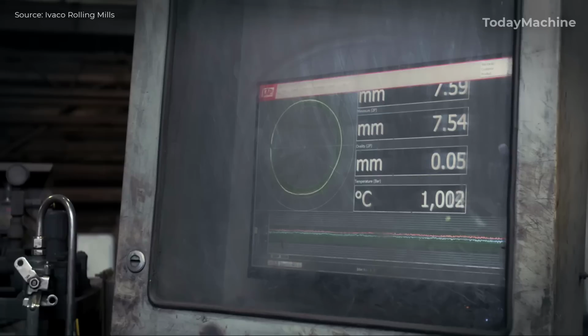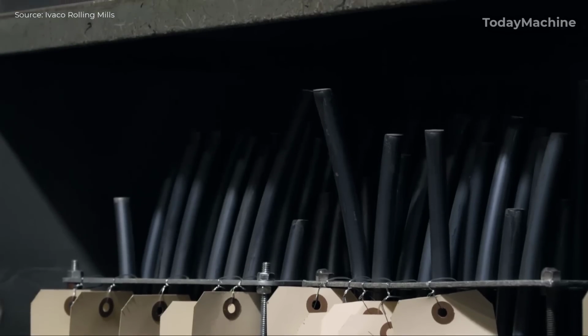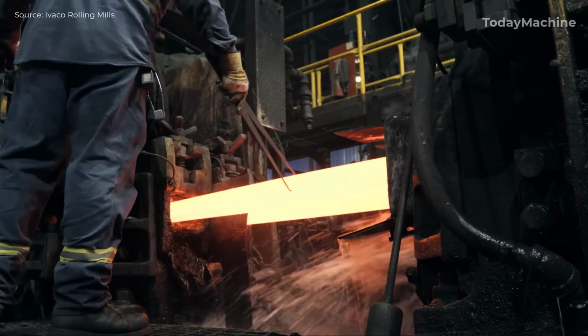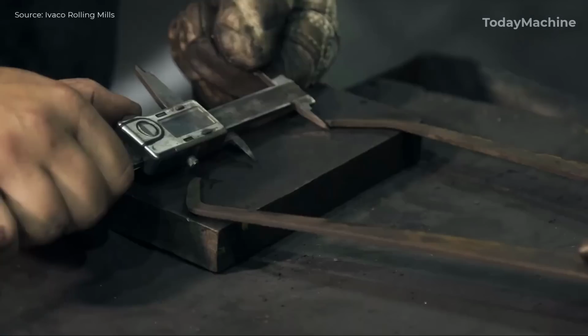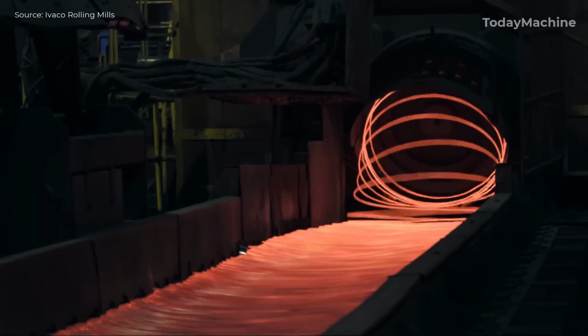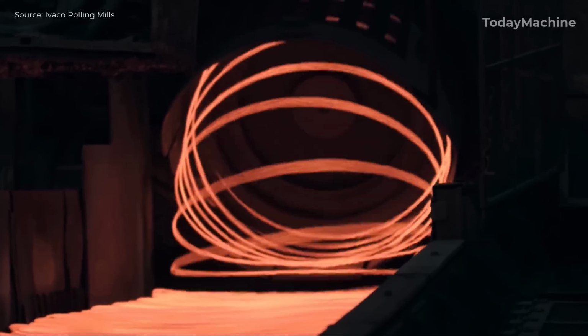The final shaping of the wire rod occurs in the reducing sizing mill, where the rod is given its precise diameter, ranging from 4.75 millimeters to 25.5 millimeters. Advanced instrumentation measures the rod's diameter and surface quality, ensuring it meets exact customer specifications. The wire rod then moves to the cooling stage, where it is shaped into coils by a rotating laying head.